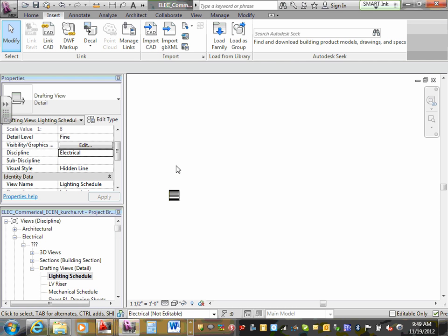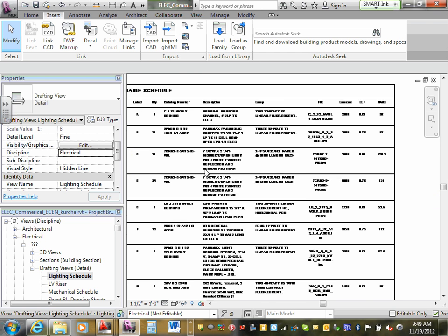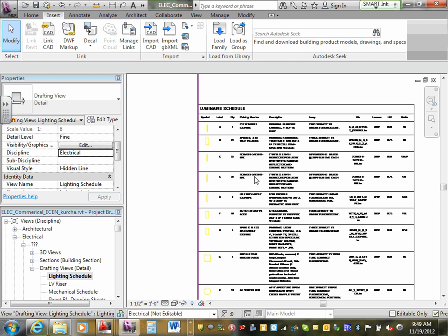After you guys are done, here's my lighting schedule. Now I know mine is screwed up because I have to adjust that. Then you drop the lighting schedule in E9. Any comments, any questions about the lighting schedule? So I created a lighting schedule drafting view, and I dropped it in the lighting schedule drafting view. The last thing, last but not the least, the relay schedule. If you have not created the relay schedule, there is a relay schedule that we have for you.